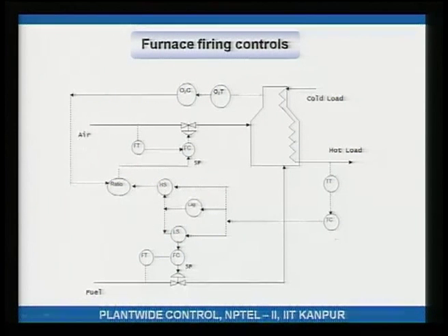On the other hand, let us say the heating load is decreasing. What you then need to do is, in this case, the fuel should go down first and then the air should lag behind. Again you notice this hatched area during the transient, or during the period where things are changing from one steady state to the next.